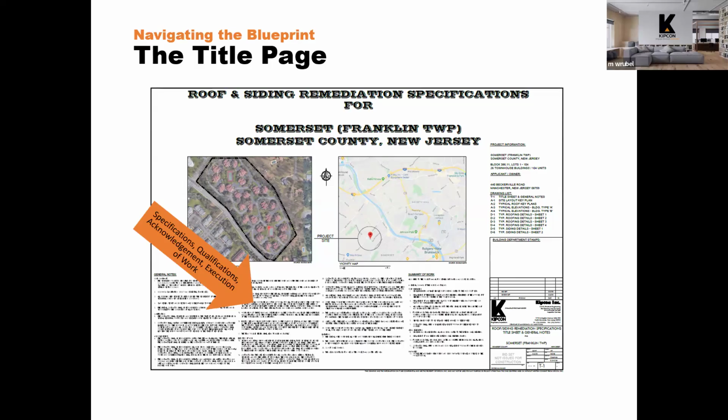There are certain notes that are related to the execution of the work. What is the basis of the plan set? Is it based on a survey? Is it based on satellite imaging? That'll be noted here. Also, if the contractor is doing a certain task on site, what's required, such as the site is required to be swept broom clean at the end of every day. Then the facilities for the workers need to be located in a certain area. So just general things like that are included here.